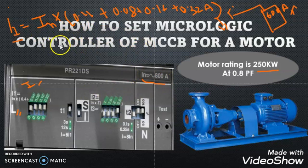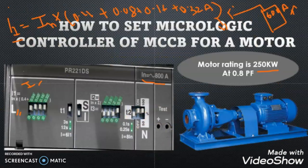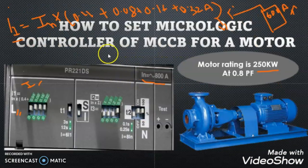But here my intention is to set this breaker as per our load current, that is 443.5 ampere, because after 443.5 ampere any current will be considered as an overload current for the motor. But if we do not set this breaker, then the current up to 800 ampere will not be an overcurrent for this breaker. So the breaker will allow the current of 543 and above till 800 ampere, and then it will trip, and meanwhile our motor will burn.